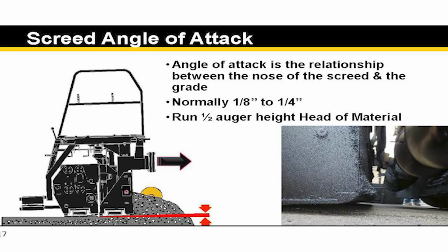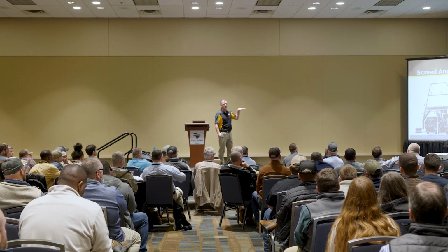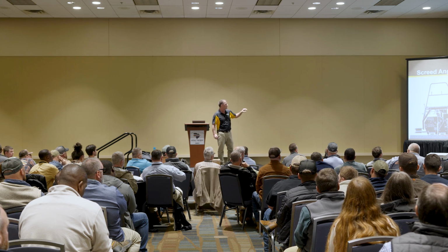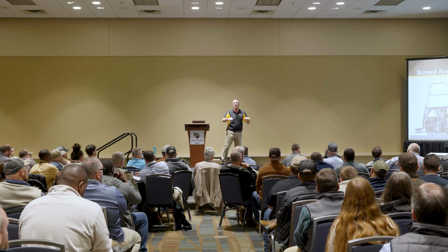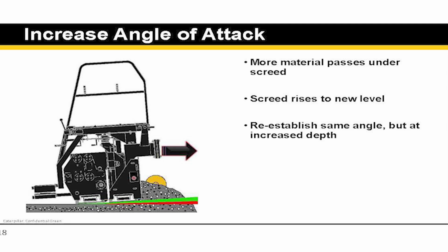Now, just to give you the quick theory on why that happens, that screed is set up, we take off from our joint, and we should be paving at a quarter to an eighth to a quarter inch, what we call angle of attack on that screed. So that gives us that little bit of nose up attitude, so that mix flows underneath and floats, if you will, supports that screed while we're paving. So we've got that angle of attack. When I raise the toe point, or toe points, left and right side, I increase that angle of attack.